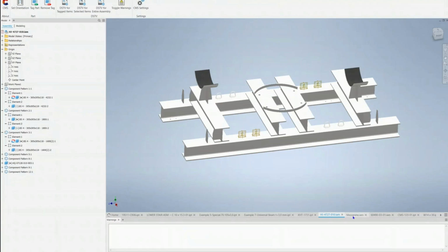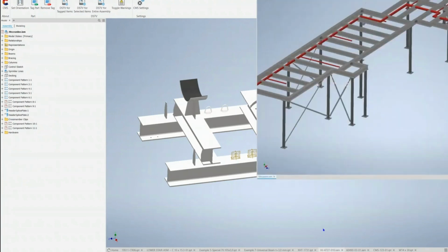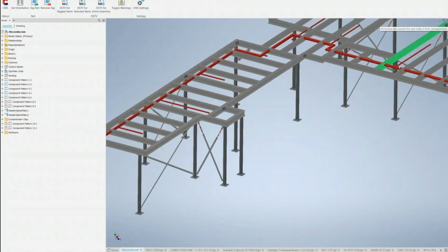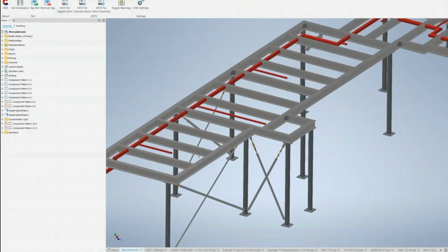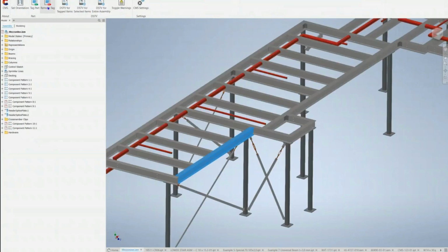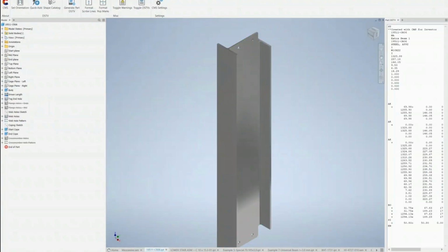Given that the shape size information was there, and all those components were placed as per the approach. The same goes for, let's say you want to work on an assembly slightly bigger compared to the one that we had before, and you want to make sure you create NC1 files only for the items that you want, right? For that purpose, what you can do is select members and click tag, as you saw over here.